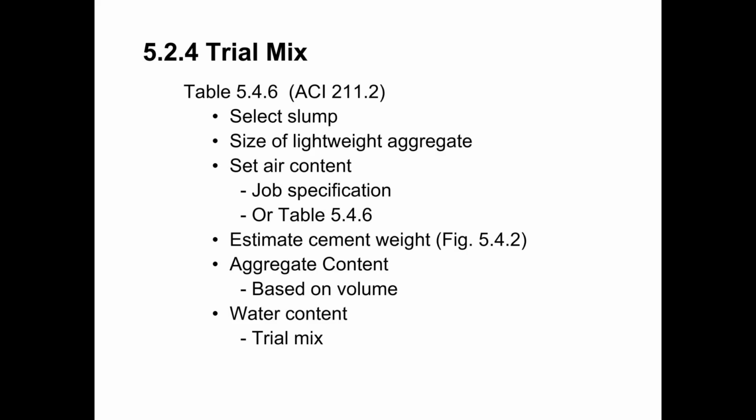And then next we're going to look at our cement weight. Now notice, looking at figure 5.4.2, for a lightweight mix design and getting our target cement weight, I'm sorry, if I said table 5.4.2, it's figure 5.4.2. You can see that this just provides a band of target in the target range.